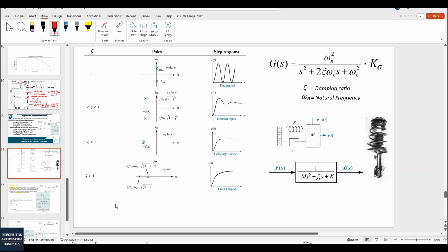All right, in this case, I will use this transfer function. This is an underdamped second order transfer function, s squared plus 2s plus 9, and K is equal to 5. So K is equal to 5 and omega squared is equal to 9. So omega is 3.